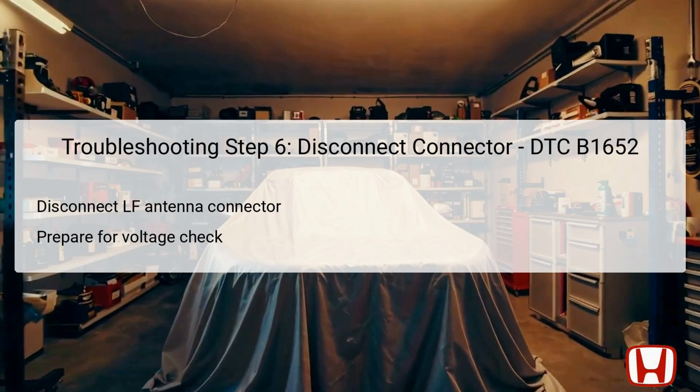Properly disconnecting this connector guarantees safety while preventing any unintended shorts or signals during the testing process. Once disconnected, one is then ready to check for voltage between specific terminals, aiming to evaluate whether the power supply is reaching the antenna as intended. This step emphasizes the importance of careful handling of electrical components to prevent damage during diagnosis.